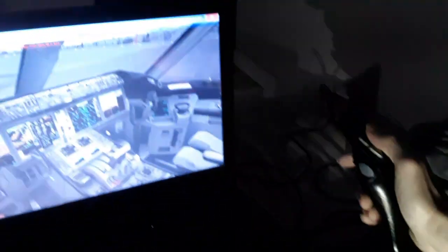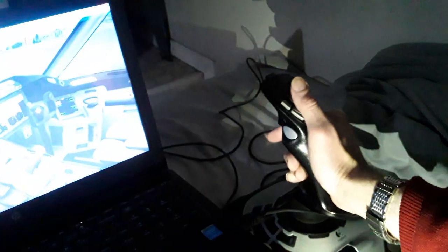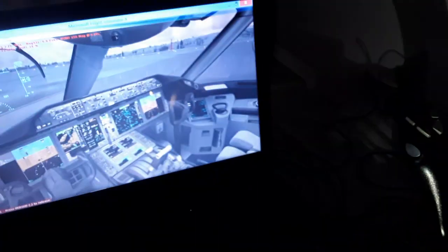So we have only the flight control computers of the Airbus aircraft. When we climb or we descend the aircraft, they limit the acceleration of the climb or descent in terms of g, where 1g is the Earth gravity acceleration. So we can climb an Airbus aircraft with a side stick up 30 degrees or 1.5 g, or a side stick down like minus 15 degrees or minus half g, as you can see. So climb 30 degrees, so 1.5 g, or descend 15 degrees or minus half g. Also in the Airbus, the Boeing has similar features.